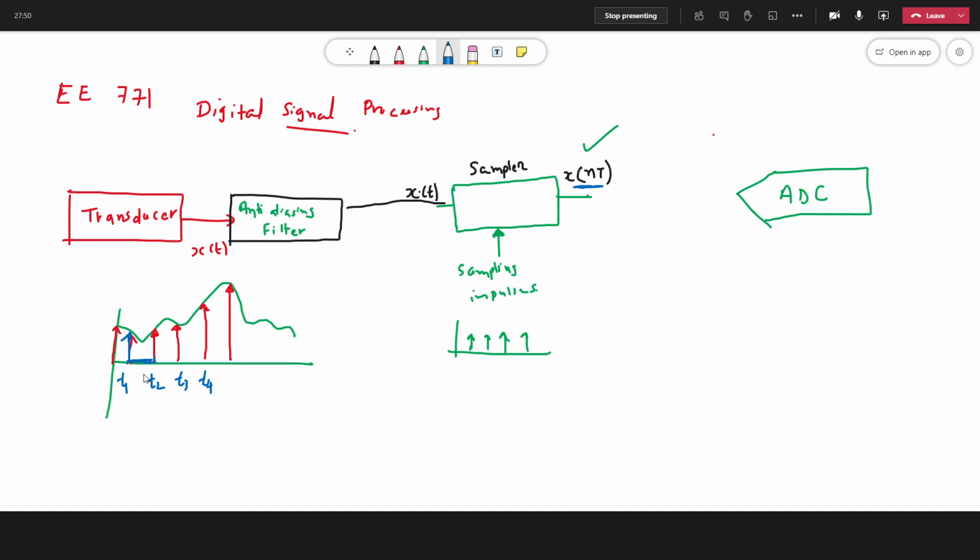If it becomes 0 before 1.1 millisecond, the ADC will again have 0 input, and the process which was initiated at t equal to 1 millisecond will fail to tell you the strength of the analog signal, the digital equivalent of the analog signal.